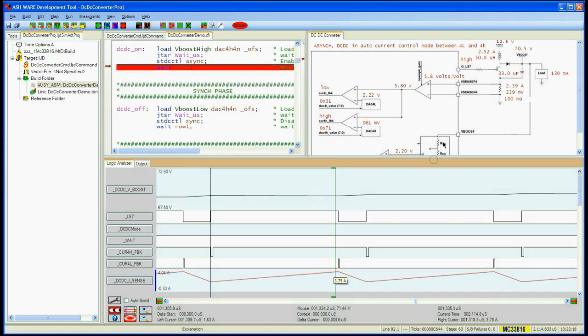This becomes obvious when the left and right vertical cursors are placed on the LS7's positive pulse's beginning and end. With LS7 on, current flows from the battery through the inductor, through the power MOSFET, through the sense resistor to ground. The diode is off, thereby blocking the current from flowing through the power capacitor back through the driver. Energy is being added to the inductor during this period.